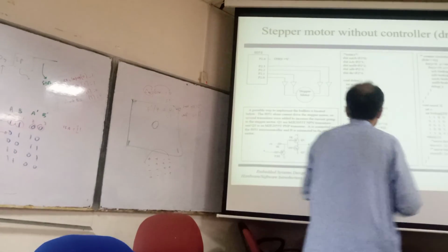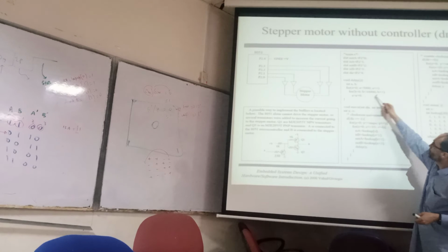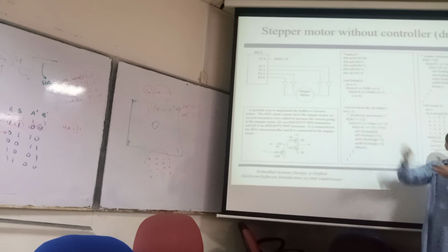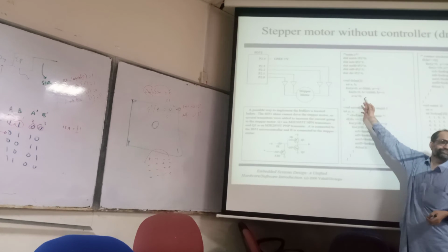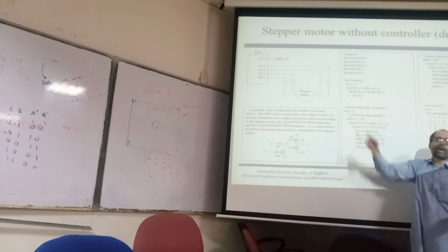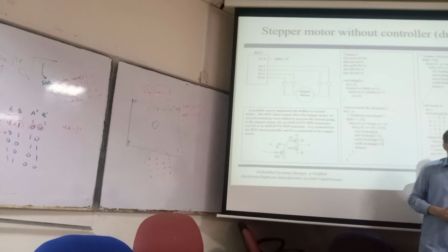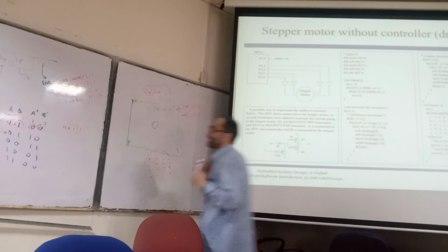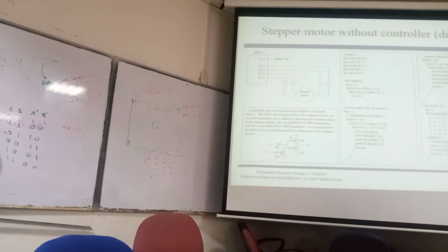Counting. Because for A is equal to 0, A is smaller than 5000, A is equal to A plus 1, you are just doing nothing here. Executing some unuseful instruction, just like a NOP. So if you want to implement this delay in assembly, we can initialize some register with very large values. We can then decrement the register, and then we compare it with 0, and when it is not equal, it will jump back to the loop. And when it reaches 0, it should exit out of the loop, and then we have a return.